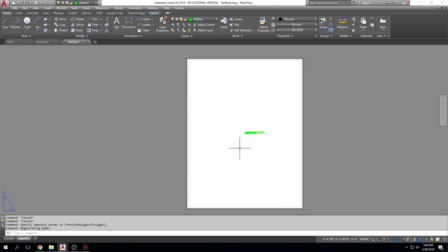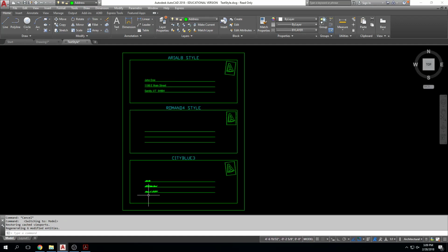And the reason it's doing that is because when we created our text here, we set the annotation scale 1:1, right? And that will filter 1:1 text height in the viewport, right? And I made the example on Monday of a floor plan, right? If you have a floor plan that's scaled at 1/4 of an inch equals a foot, and you need to put a bunch of annotation on it, all of that annotation is scaled at 1/4. Now, if you have an enlarged floor plan on the same plan that's scaled at 1/2 inch, you'll also, on top of that 1/4 inch annotation, have 1/2 inch annotation, right?